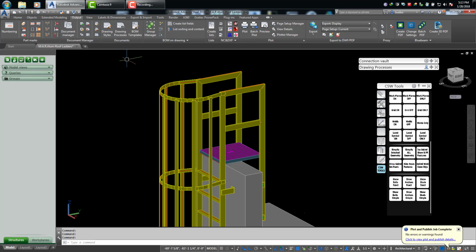for the shop is obviously to be fabricator friendly, number one, and also to have minimal clutter, giving all the information but nothing else. And typically any drawing style, with the exception of gather sheets, out of the box on most of these parametric detailing softwares, most of the drawing styles are going to be cluttered with just pretty much everything thrown at it, as far as dimensions and all kinds of stuff that you really don't need, and you have to pick through and delete, and it becomes very time consuming to basically scrub the drawing styles out